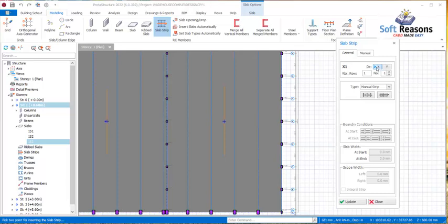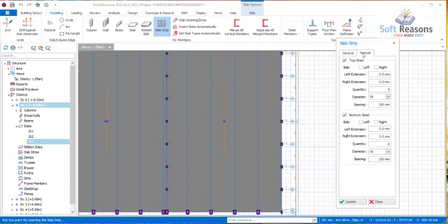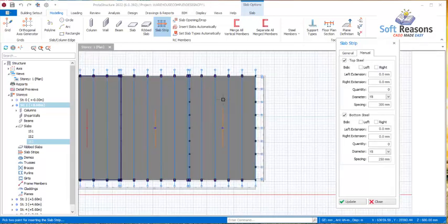All right, so having checked the direction I'm going, I may be able to take it to Y directions. If I take it to Y directions, come over to these provisions, you will notice in the Y directions, which is the vertical directions, we have both ends of the reinforced concrete slab to be discontinuous. So you have to check here and check here, as well as check here and check here.